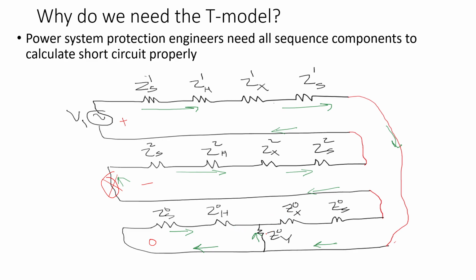That's very important. So for the positive sequence, I can go to the next slide and redraw it just to eliminate any confusion. This is for a line to ground fault. So you draw basically the source, then you draw the system impedance, then the transformer impedance, the high side, then the low side, then the other system.